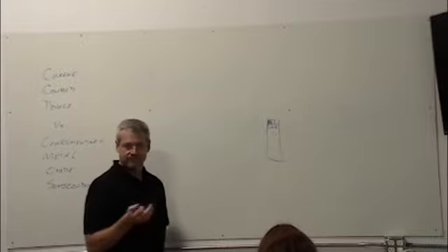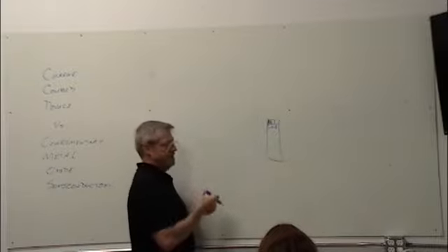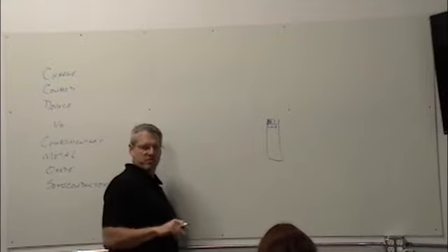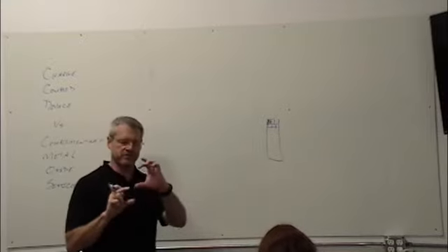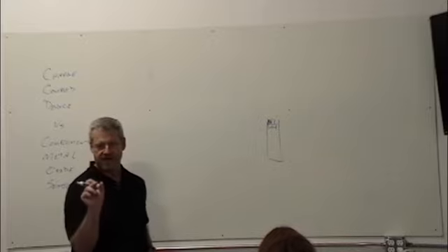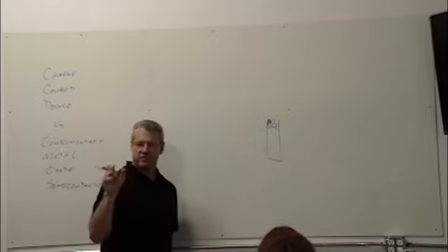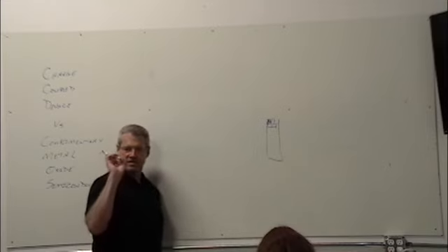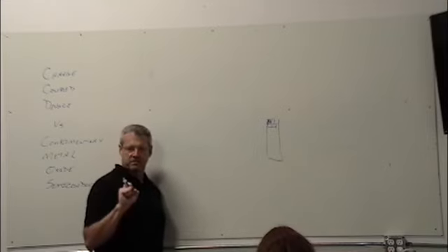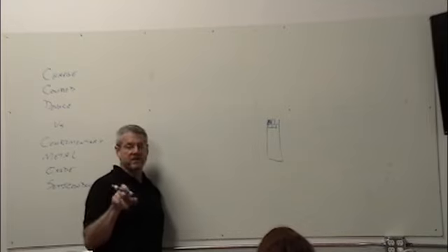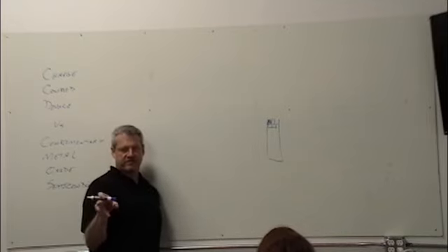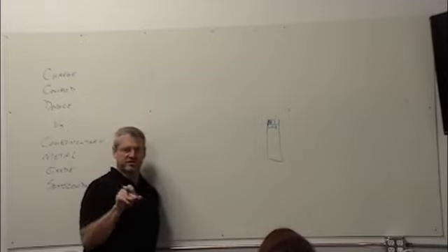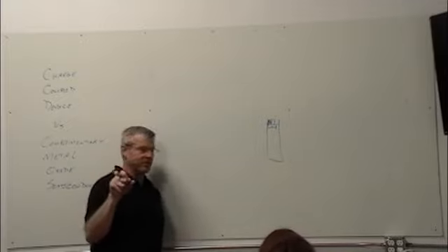Whatever my feature size is. So if I've got regular bricks that are around 8 inches by 3 inches, but there's a half-inch gap in between each one, I want to be able to see that the half-inch gap is different on each one. So that means I need to be able to see a half-inch size pixel. I don't have to Nyquist that half-inch pixel, right? I need to Nyquist the brick and the gap together so I can discern the 2 apart.